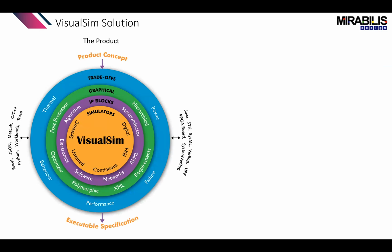Now, what is the VisualSim solution that enables all of this? The product really takes in a concept. There's an underlying simulation engine which contains a discrete event simulator similar to Verilog or SystemC or any of those kinds of tools. It has a large library of 500 plus components. These are the components that allow you to very quickly assemble your particular system. Now, there are some other features. The key feature is that it is fully graphical, so you're not spending a lot of time debugging C++ compiler issues. You're spending more time debugging your architecture.